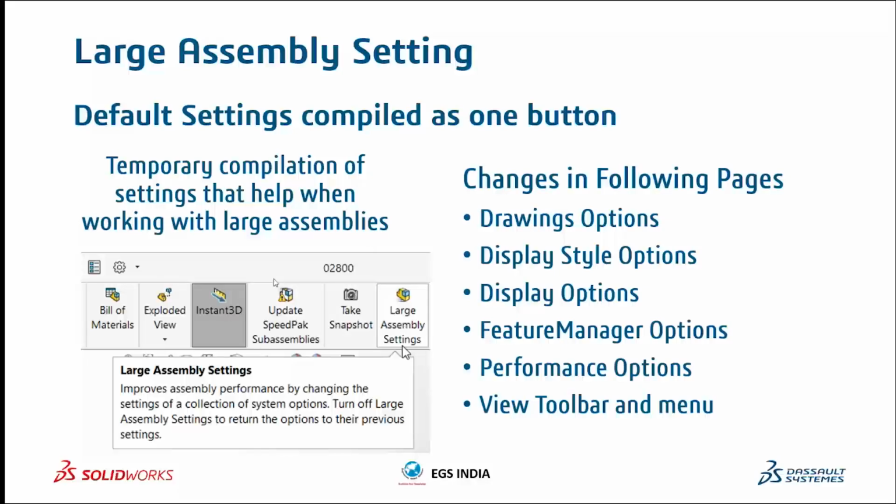We always recommend having this on when working on large assemblies, since you don't need to specifically go in search of options that will make your performance better. This is a compilation of it, and another benefit is that it's temporary. So within a click of the button, all of that can be reset back to its default settings.